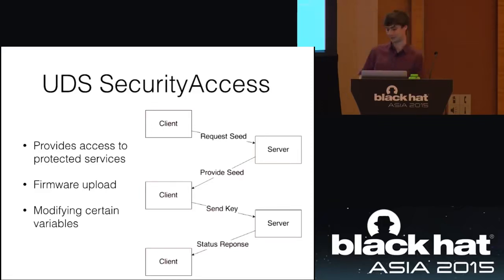But this protocol doesn't look terrible until you start breaking down some of the assumptions they've made. The first one is the seed is fixed. Now, the reason that they give for this is that they didn't want to put the algorithm or some actual important key in every controller. So instead, they just put one seed in every controller, and it'll just send you the same seed every time. So, okay, that already means one thing, which is that the key is fixed. And that means this is 100% vulnerable to a replay attack because you just send the same key back every time. You don't even need to look at the seed. It's the same thing.